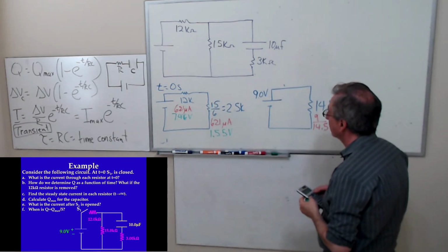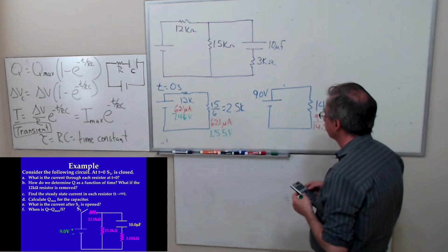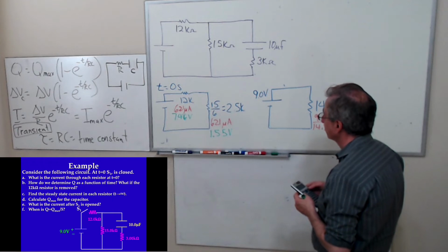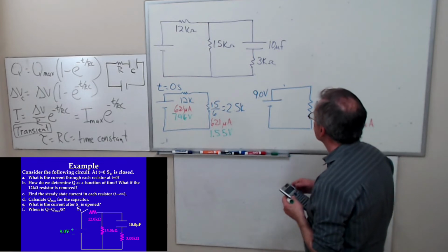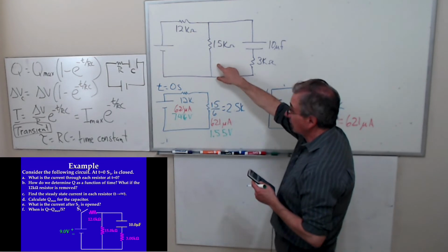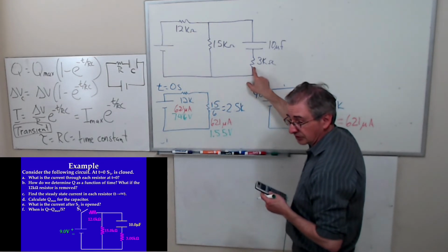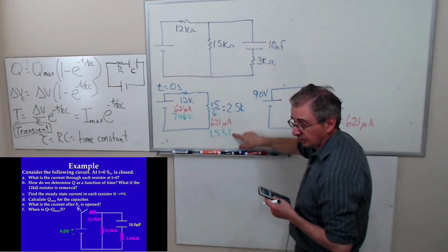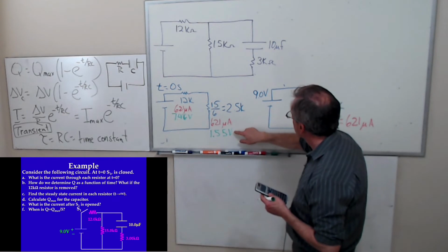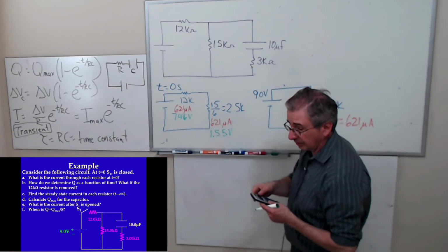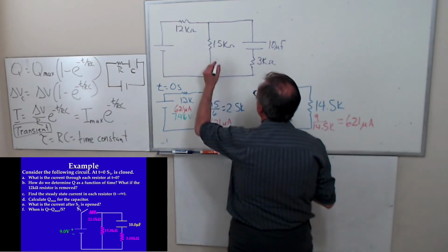Hey, Professor. If we were to separate the two resistors in parallel, the current across them would not be the same, right? For these two, you mean? Yeah. So I'm going to go through and get these values now. Right? Because I know the voltage, and that's constant across them. So I'm going to take this divided by 15K. Well, let me write the voltages down.